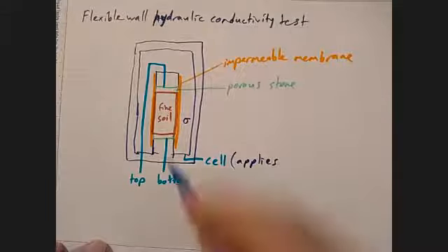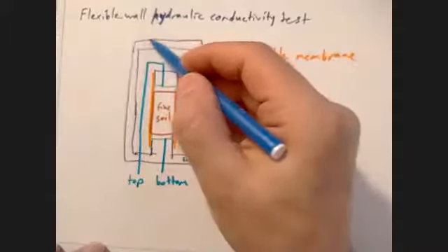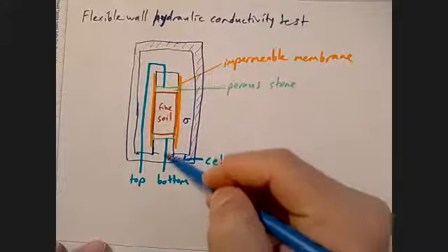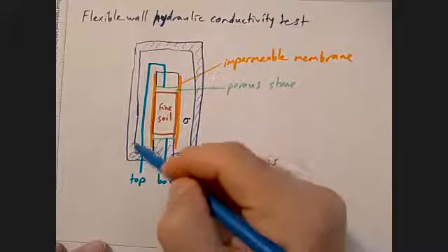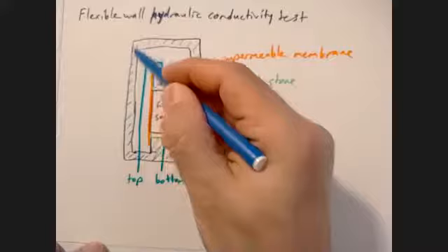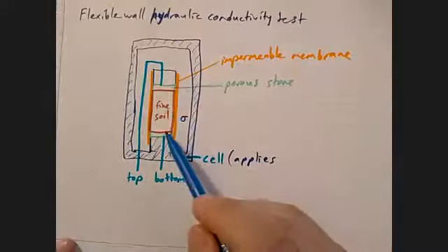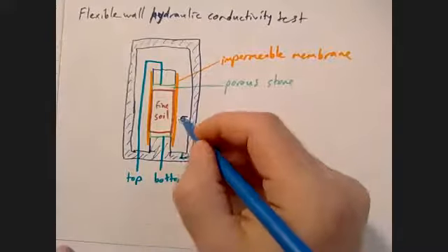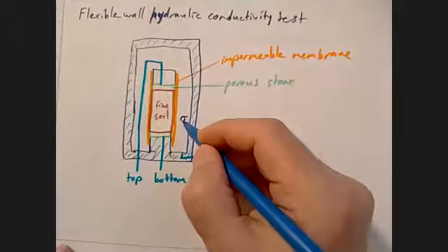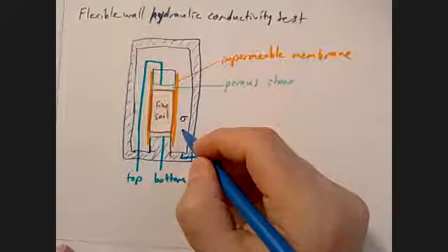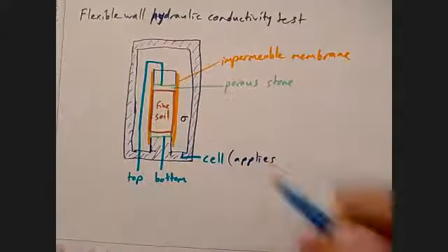You have a box, a container in which there is fluid, and because you have a rubber impermeable membrane surrounding the soil which doesn't offer resistance, once you apply fluid pressure on the outside, it cannot go into the soil, but it is applying total stresses.